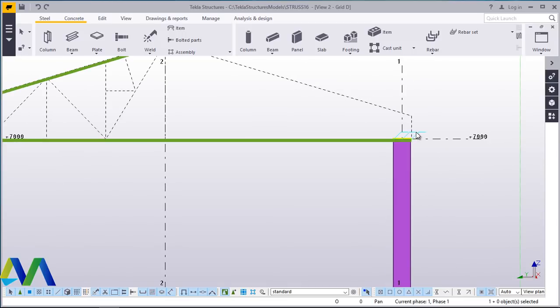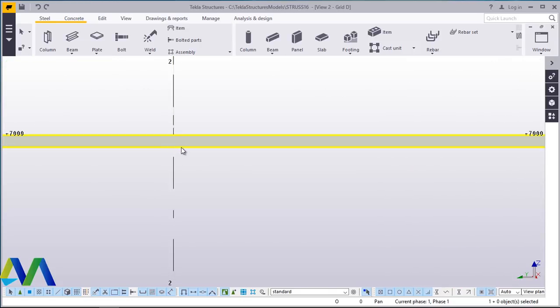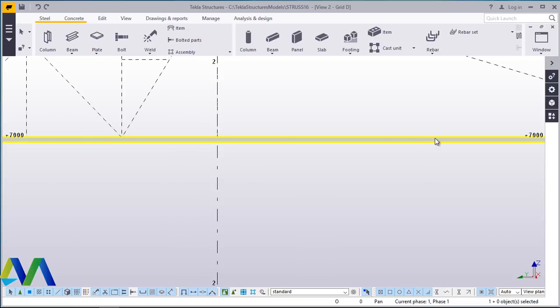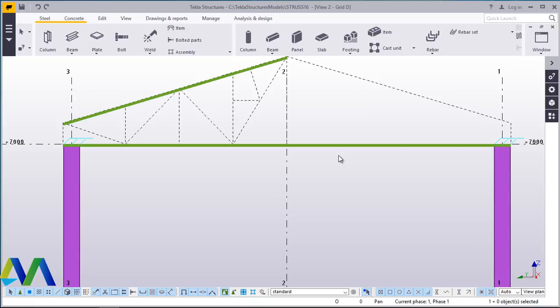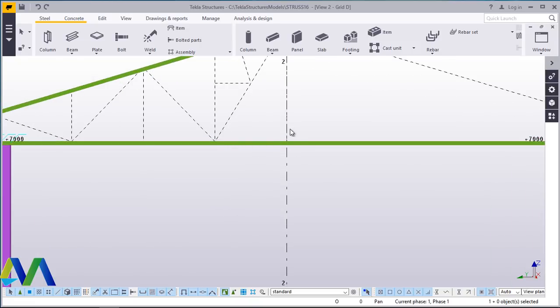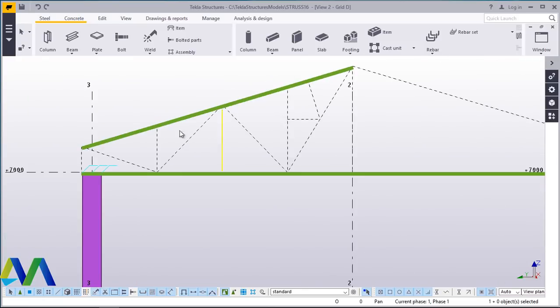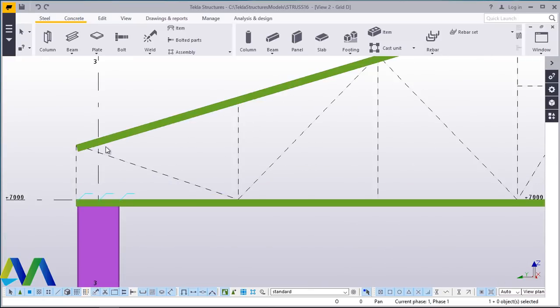Now let's assume you'll be using 12 meters, then they will meet at this point and the joint will be welded. So on the drawing I'll just put it straight full length, but on fabrication and while detailing we will be able to terminate in between here to have 6 meter or 12 meter and another extension at that end. Now from here we want to extend this bit to overlap or to have an extension down here.